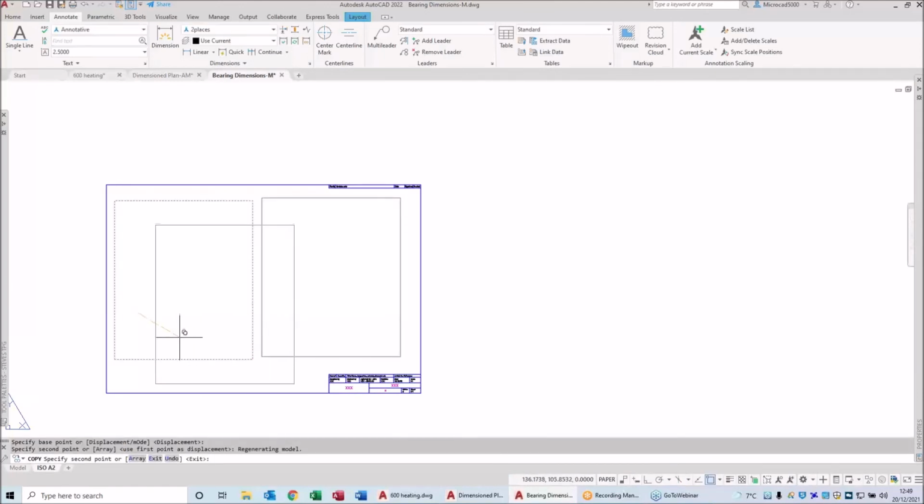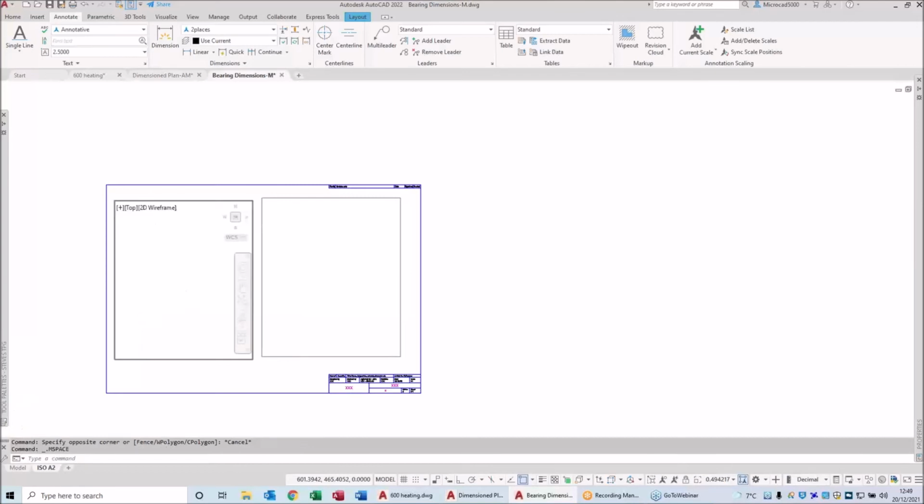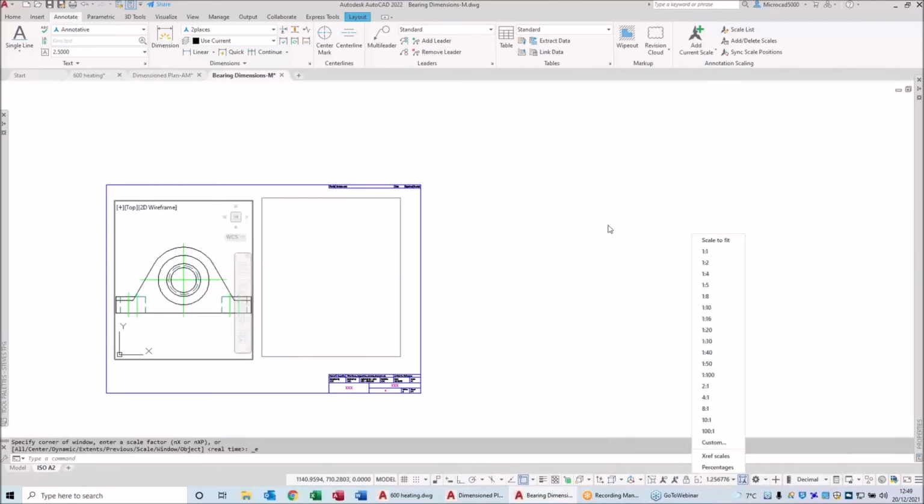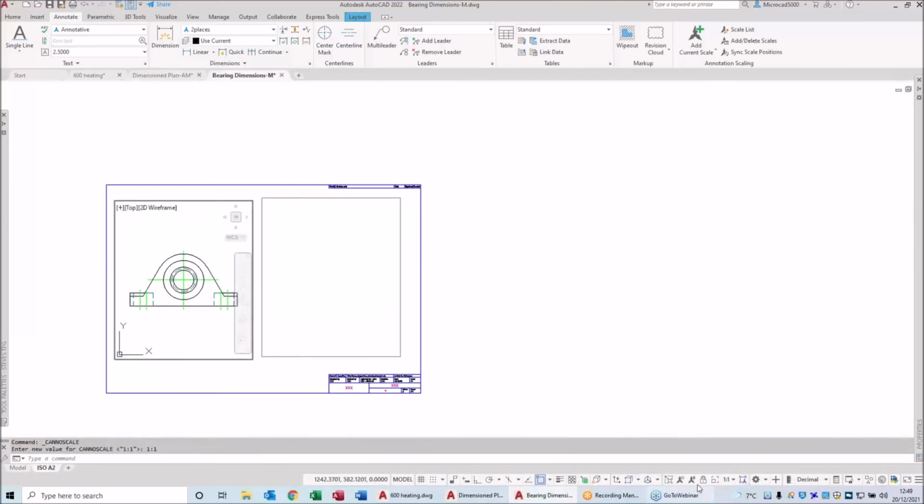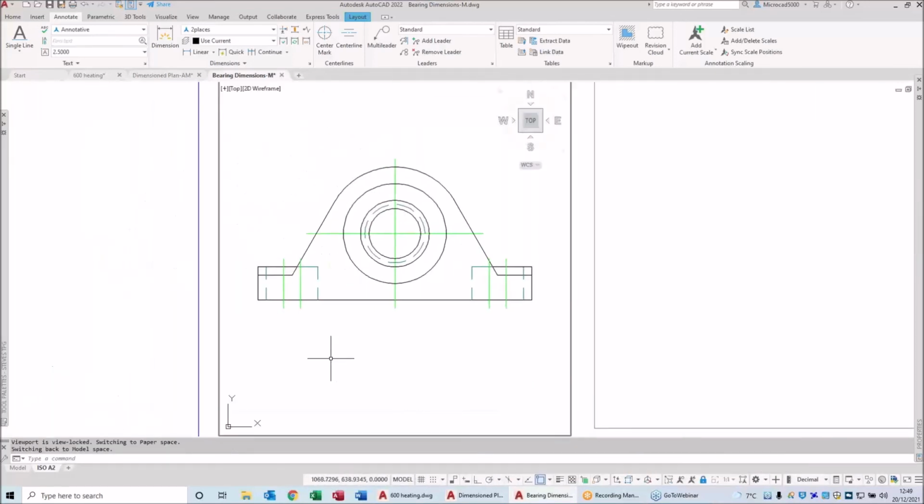Look. Now go into this viewport, double click. Set this viewport scale to 1 to 1. Okay, and padlock it. Right. Now look at your line types. Somebody screwed up on the line types in this drawing file. I press the regen key there. Just the hidden lines show correctly. The center lines have been messed up. But I'm going to set it.